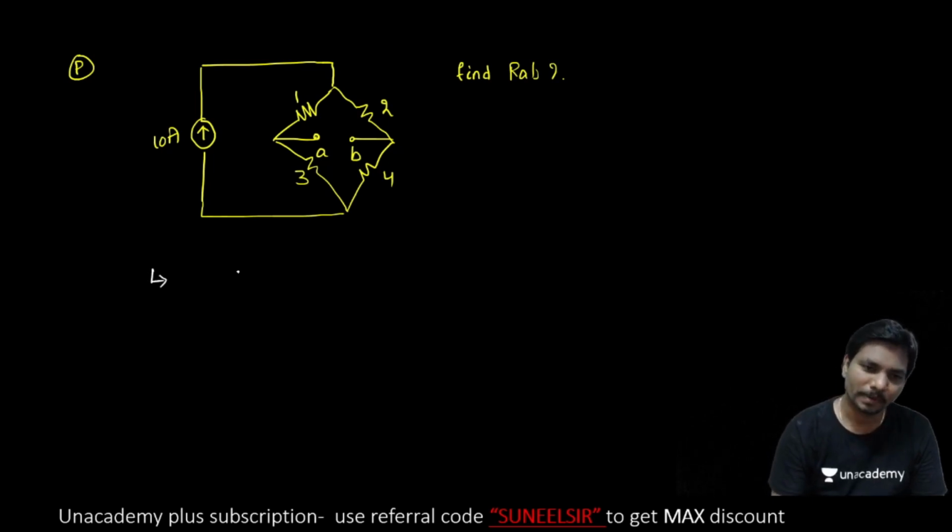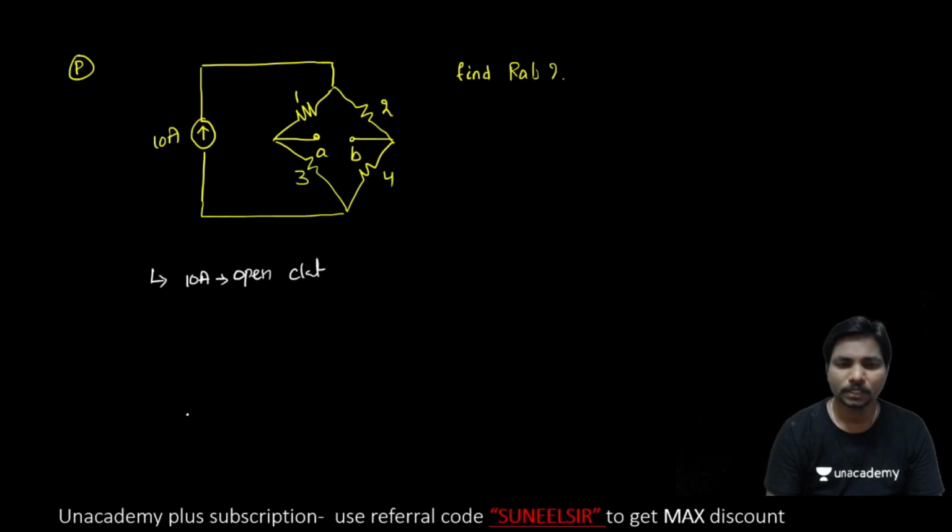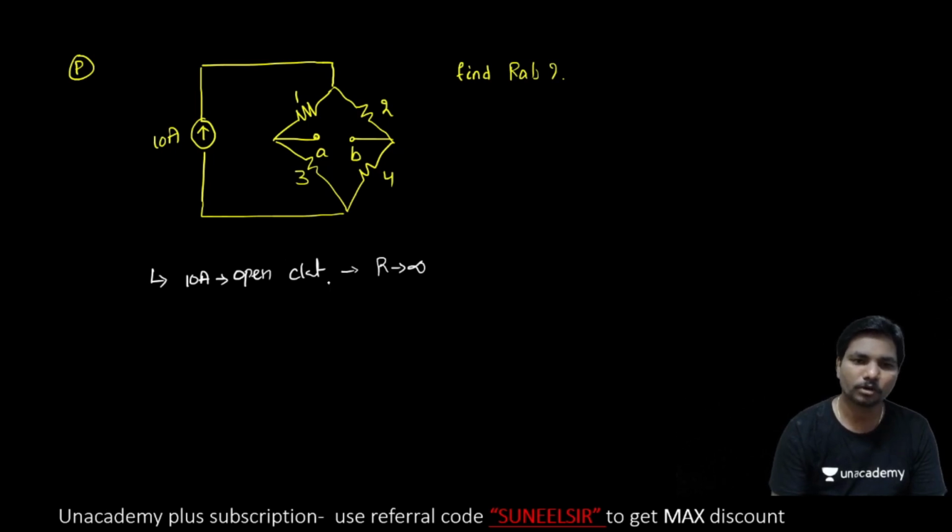So here we have a current source, that is an open circuit. Because we have to replace it with its internal resistance. We are finding the resistance, so this one also we have to replace with a resistor only. So it is an open circuit, meaning infinite resistance. Okay, so we have to open that one.